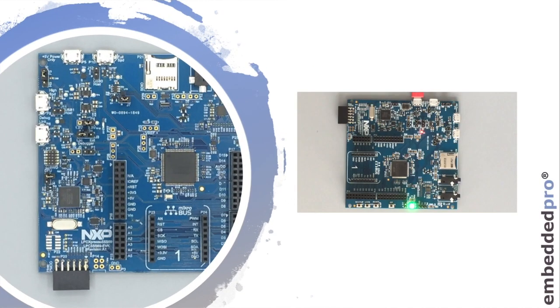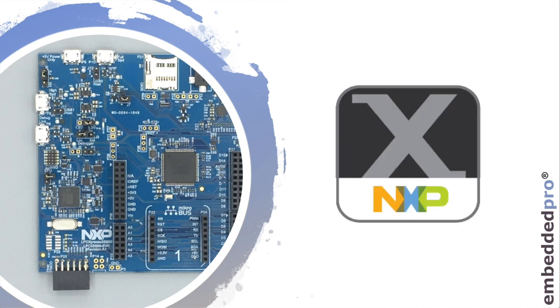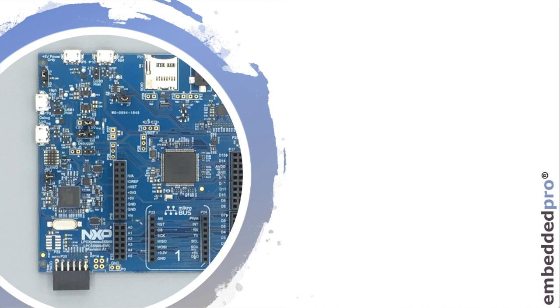I just showed you how to create a new project in MCUXpresso IDE and to use the SDK components to read the switches and control the brightness of the LEDs on the LPC55S69 EVK. To do this, we use the pins configuration tool inside MCUXpresso IDE. I'm sure that you'll be able to do this.